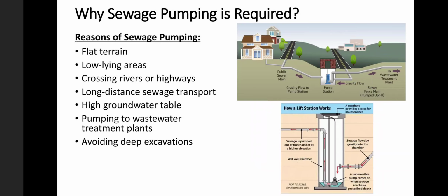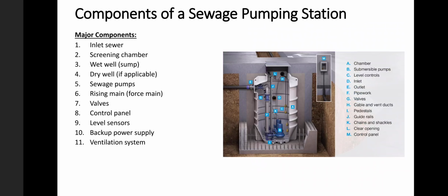And also in case of crossing a river or highways from one end to another, we have to use sewage pumping. Also for longer distance sewage transportation, and in case of a higher groundwater table, we must do sewage pumping and thereby avoid deep excavations.